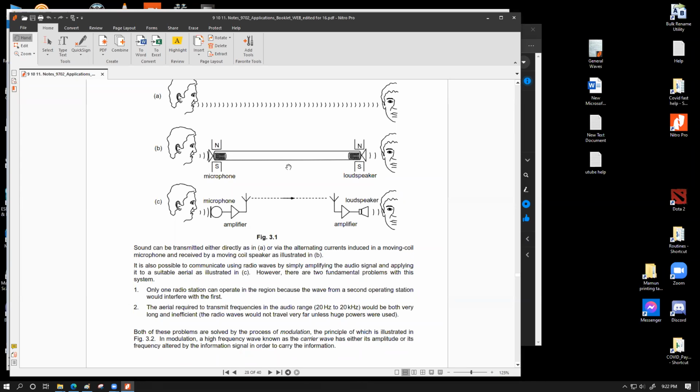So the intensity is proportional to frequency squared, and we're not getting any benefit from that aspect, because the frequency being very low means the transmitted signal itself will be very weak. It cannot be powerful. And that's one thing. The other thing is that as the signal travels further, it will definitely undergo attenuation and spread out. Its signal strength will decrease. So if we want the signal to be transmitted over large distances, the initial signal strength has to be significantly strong, so that it can actually be detectable over large distances as well.